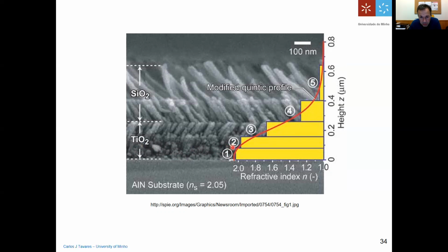And if you increase the porosity of this titanium dioxide layer, it's divided actually in 2 or 3 parts: you start here with low porosity, you increase the porosity, and here you increase it even more. So it's like you are making a gradient in titanium dioxide in terms of porosity when you go from the substrate to the top. You can do this very easily just by increasing the flux of atoms, okay?